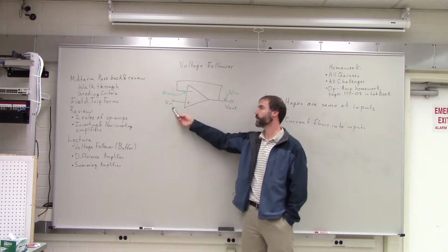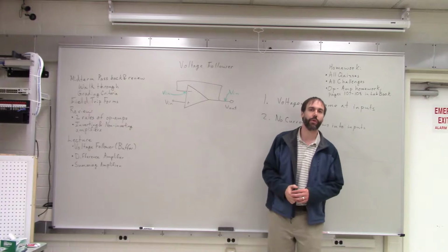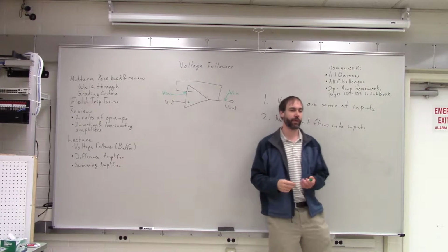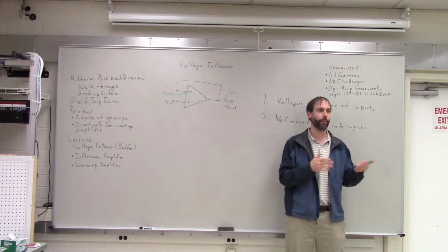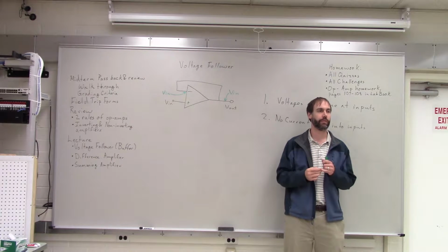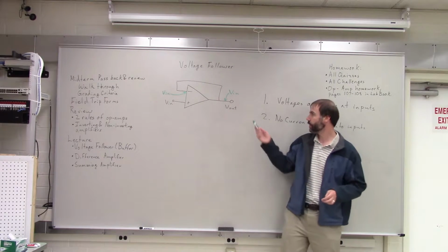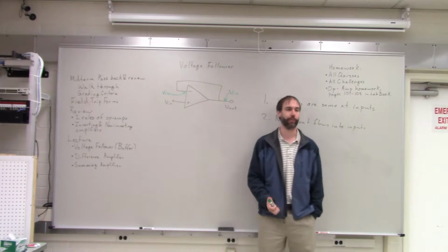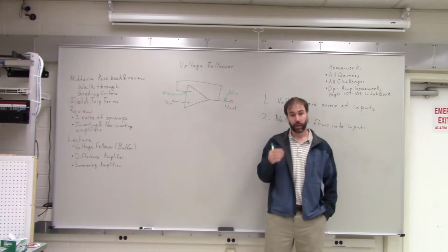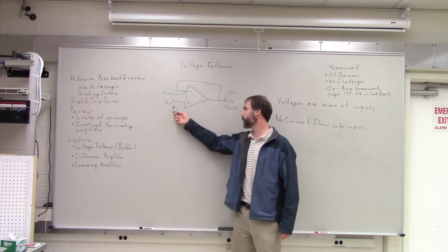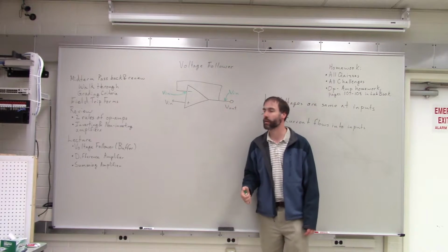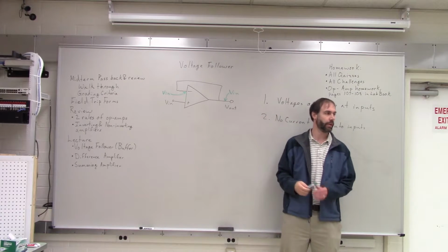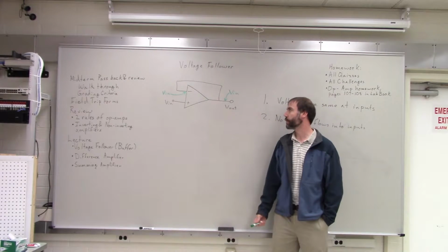The voltage out is the same as voltage in. So when we've made other amplifiers where we don't get any gain in voltage, what did we gain in? Current. So you could also think of this as a current amplifier. It draws almost no current at all, and the output can have quite a lot of current coming out. So you could see this as a current amplifier circuit.